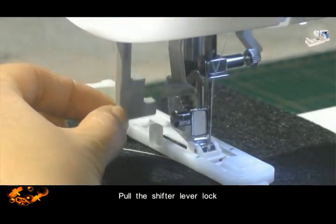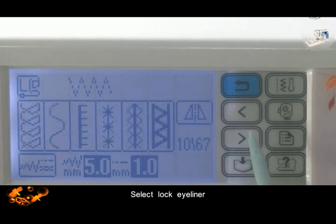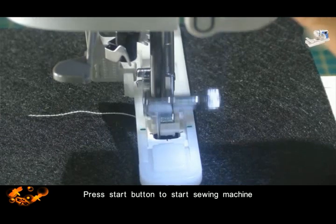Pull the shifter lever to lock. Select lock eyelet. Press the start button to start the sewing machine.